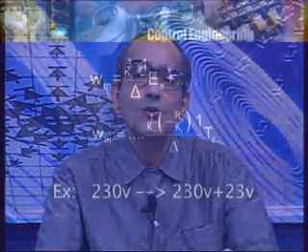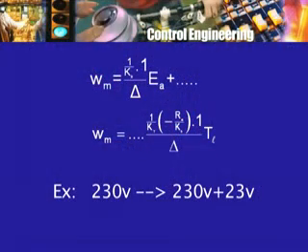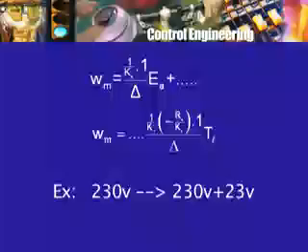And we had already thought of how to do it. We take the voltage from the tacho generator and connect it as one input to a device which we have called the comparator or the error detector, to which we give a constant reference voltage as the other input. This device produces therefore the difference of these two, ER, the reference signal, or R of T in general, minus the feedback signal, in this case the tacho generator voltage, and the difference is then amplified. That is how it appears on the block diagram. In practical terms, that difference voltage will somehow change the field current of the generator which supplies the armature of the motor.